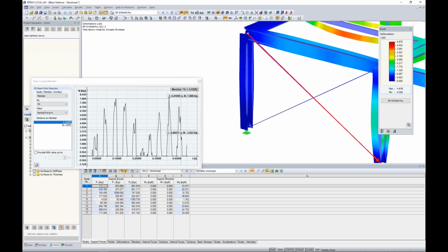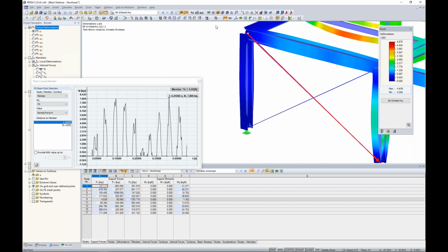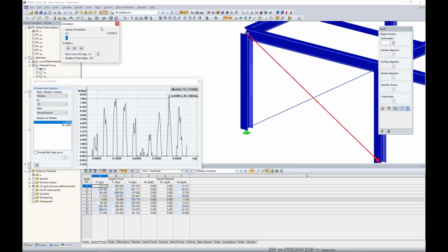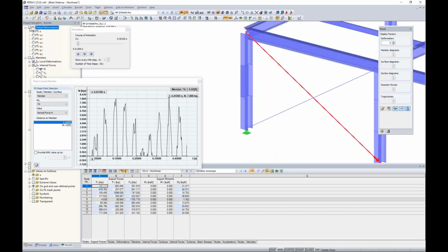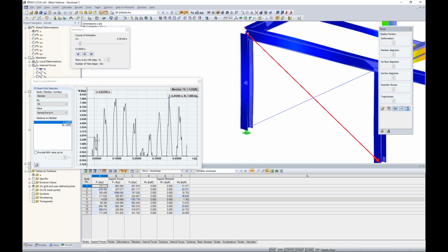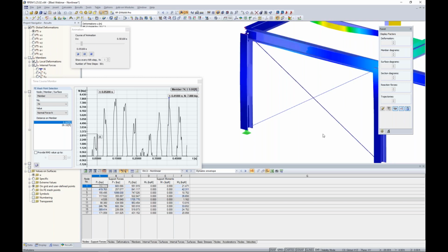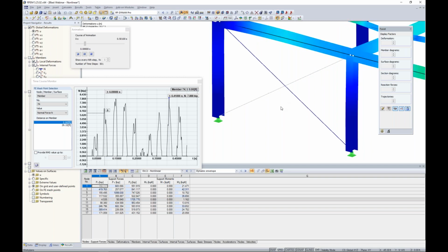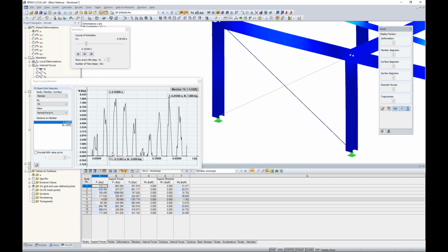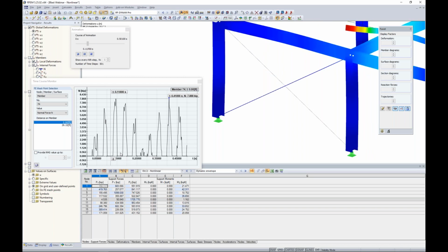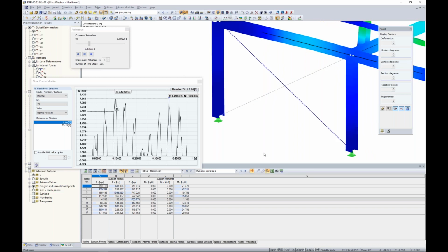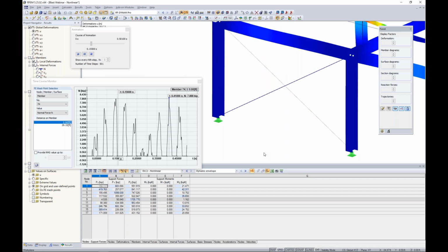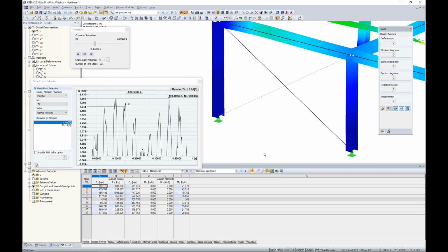We also have the ability, if we take a look at our results tab here, and let's activate the animation. I thought this might be interesting for you guys to see, that when I go ahead and run the global deformations here for the structure, you can actually see the element, and let me also turn this into wireframe view. These two elements are deactivated and activated, so you can see them graphically turn on and off as we move through the total duration of this time history analysis. So certainly a big advantage here if we have those nonlinearities that we want to account for with this blast analysis or any type of nonlinear time history, we would want to utilize these nonlinear solvers.